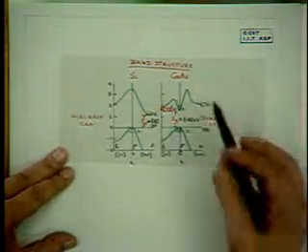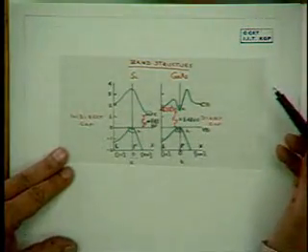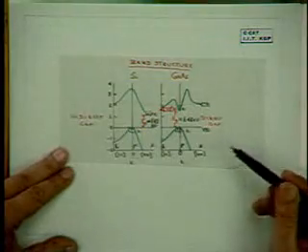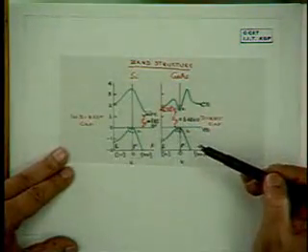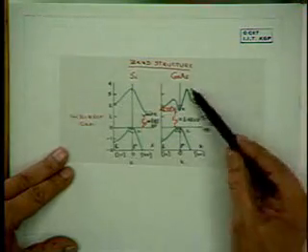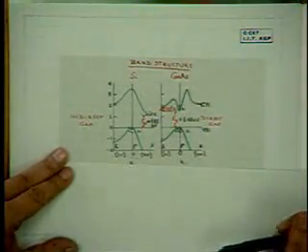In the case of an insulator, the band gap is much larger, of the order of 4 or 5 electron volts. In the case of a semiconductor, typically silicon, the band gap is 1.12 electron volts, whereas for gallium arsenide, the band gap is 1.42 electron volts.